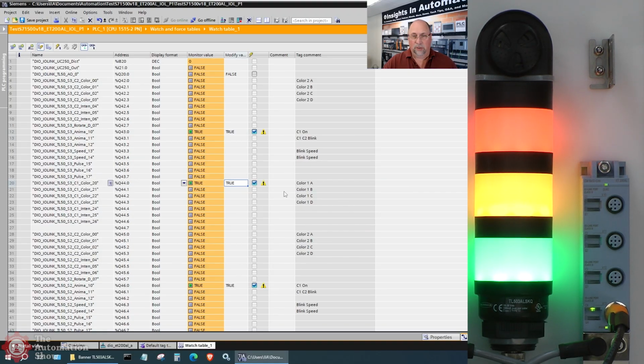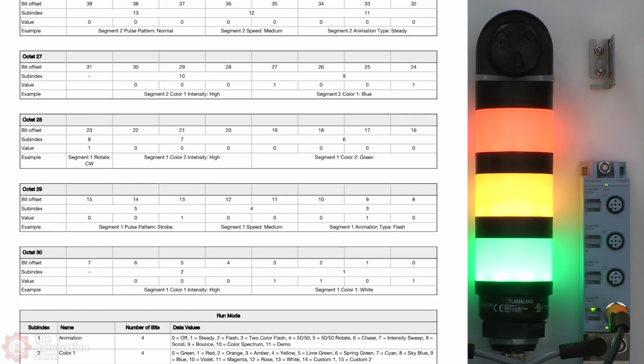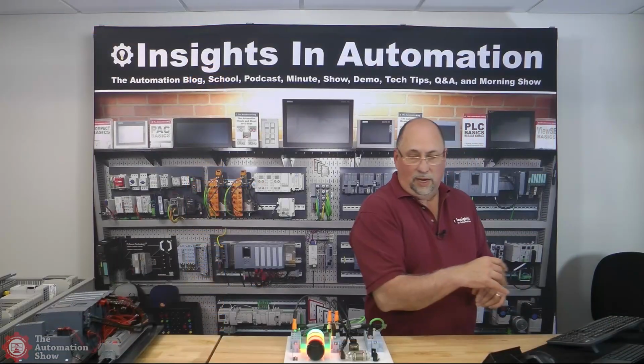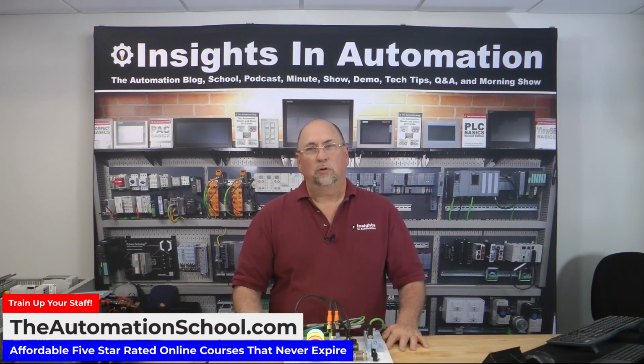Okay, red. So, yeah, again, I'll put up a picture of the tech sheet I was using from the vendor to try to figure out how to use this. But you can see here that with the power of IO-Link, you can actually use multicolored LEDs. These LEDs can flash, they can strobe, they can do all kinds of things. This would not be possible with a couple of digital outs. So with that, that's how you can use IO-Link with the ET 200AL.